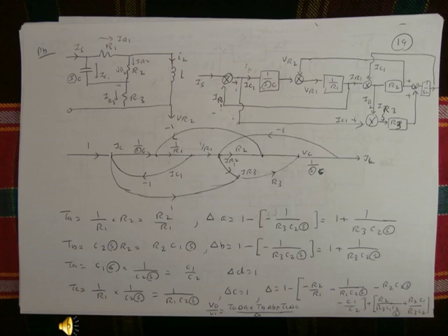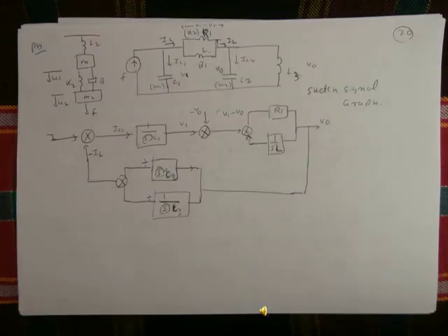One is the equivalent diagram, so you can see the masses M1 and M2. M1 is held by the springs K1 and K2, and also M2 is held by the spring K2 and the shock absorber B. The M1 velocity is U1 and the M2 velocity is U2. So this is the mechanical diagram. We can draw the electrical circuit diagram. In the electrical circuit diagram, the input is similar to the current, and then you can see the equivalent electrical circuit diagram. This electrical circuit diagram we can represent by the block diagram. You can see this. The next one will be this equivalent block diagram.